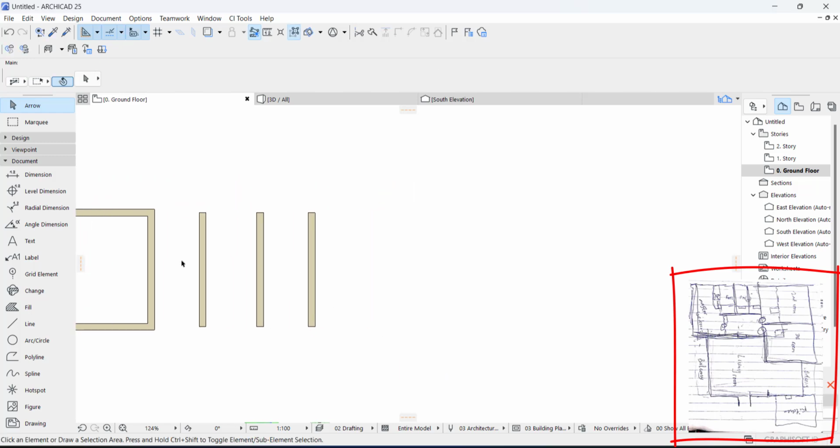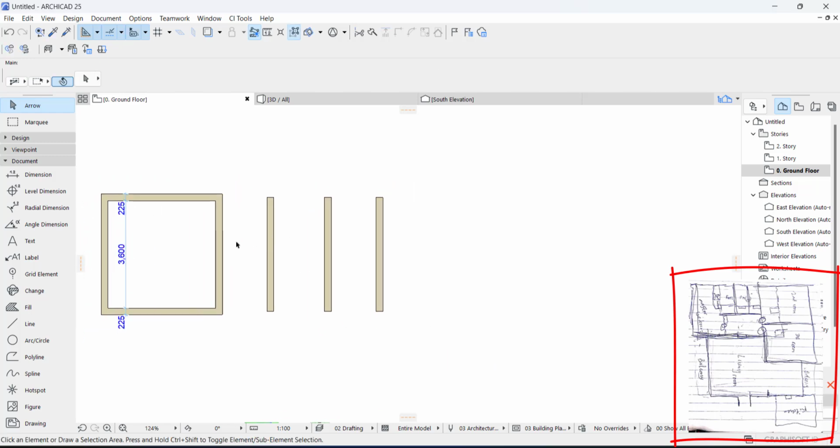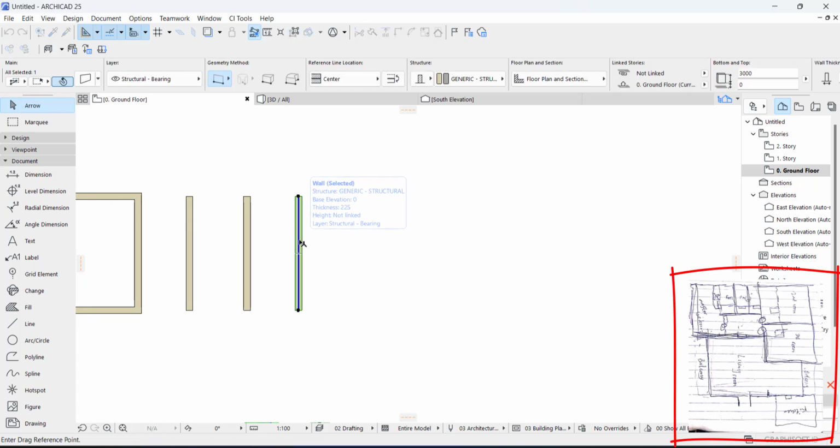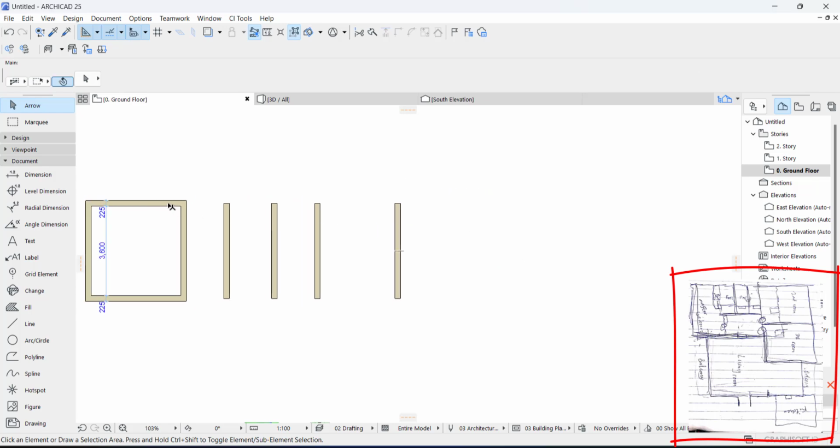Okay, so this is the master's bedroom, this is the master's toilet space, this is the bath, and this is the toilet. Okay, and then this is another room. So the width, let's just assume it's 3600. So I'm going to say 3000, or let's just make it 3000, so it's not competing with the master's. 3000, I'll add the 225, 3225. Okay, so now that's the end for that part.